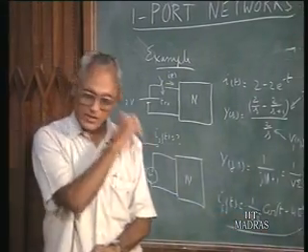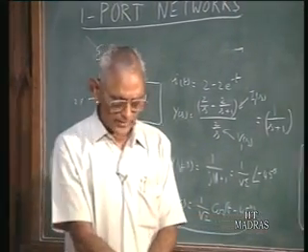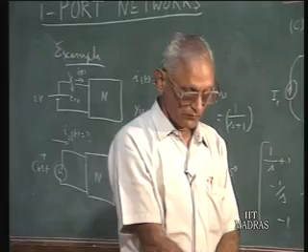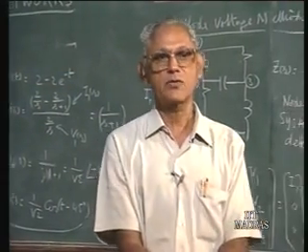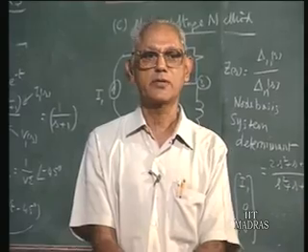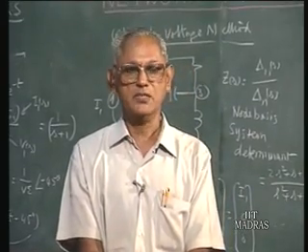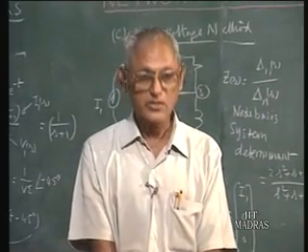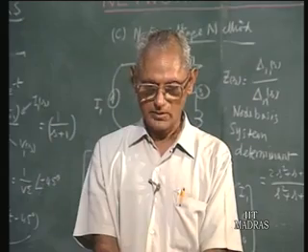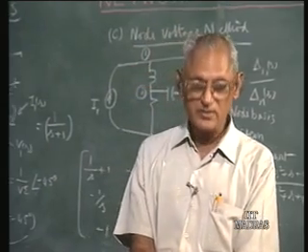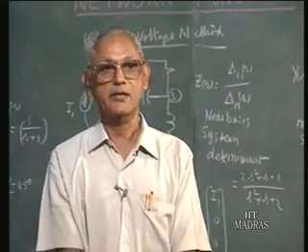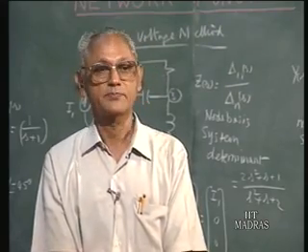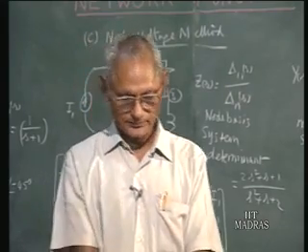So in this lecture we have acquainted ourselves with the general nature of a network function. We said a network function is nothing but a system function applied to networks, the ratio of the Laplace transform of the response to the Laplace transform of the input with 0 initial conditions in the system, and such network functions are defined only for linear time invariant networks with 0 initial conditions, of course.